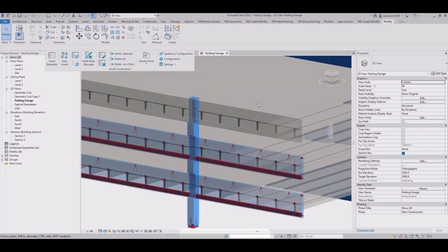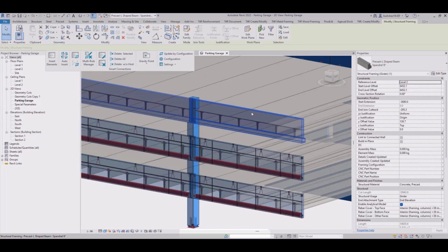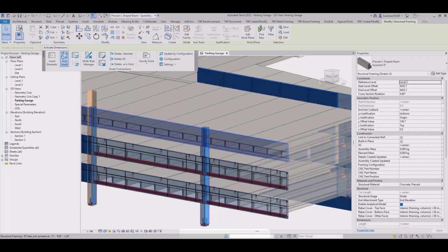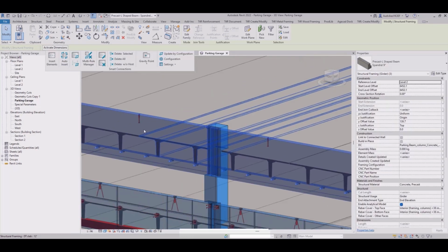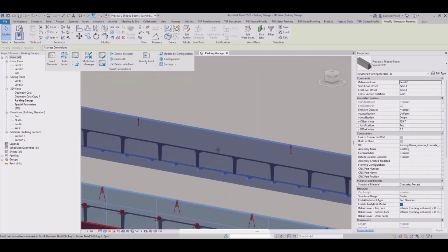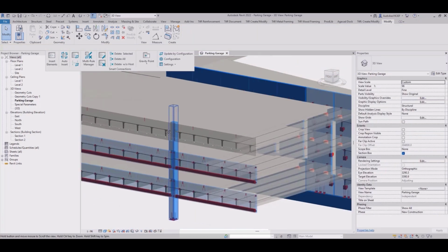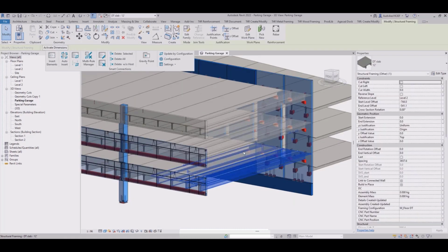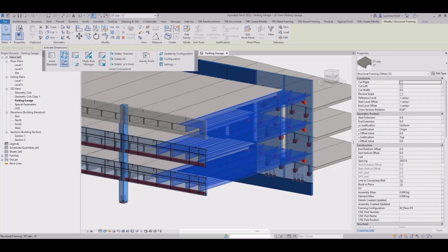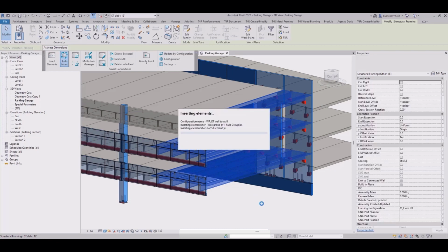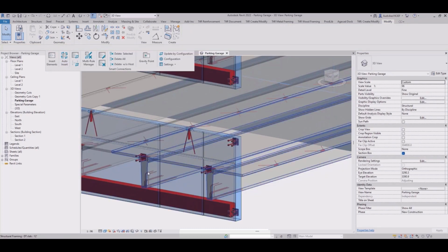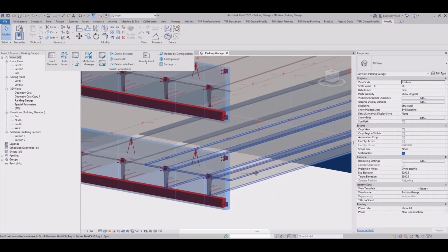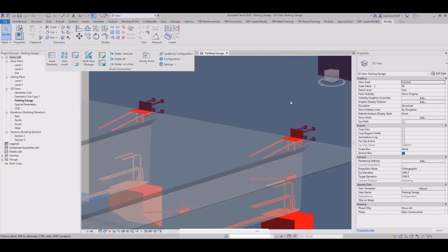And here is a sample with this girder, and again families were placed by the gravity point, or we have these cuts at the bottom of this. Alright, and we will pick now a couple of double T slabs, press Alt Insert, and we have connections added right where we want to have them, where we have steel plates, and also we have the connection between double T slabs.